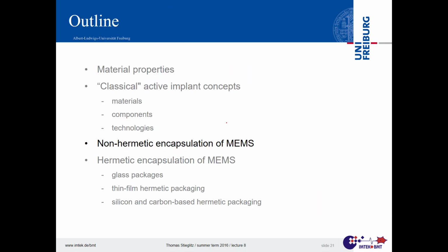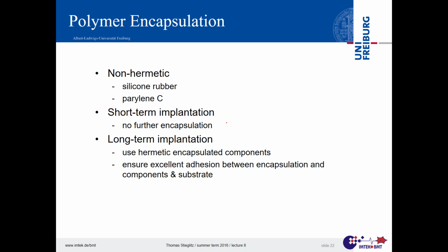So what about non-hermetic encapsulation? So something where water vapor can get through. I already said it must stick like hell to be stable. We have silicone rubber as a material class, and Parylene C. Silicone rubbers are the most favorite materials for that, even though they got a bit of a bad reputation some years ago.